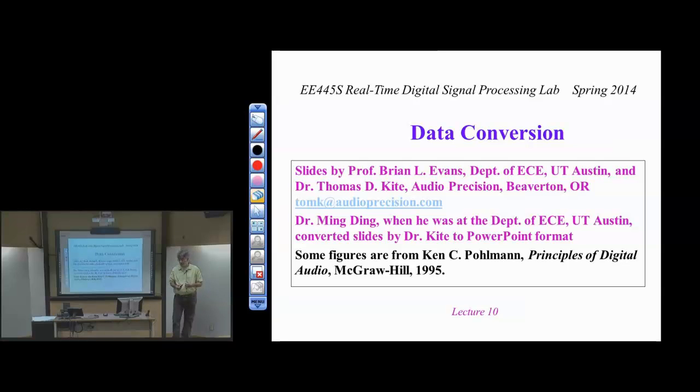The opposite would be, as you're listening to this, we now have a discrete time digital signal, and you'd like to play that back over headphones or possibly speakers. We want to convert that discrete time digital waveform for the audio back through a digital to analog converter, and then through a piezoelectric or some other device that will take the current and voltage from the digital to analog converter and get it back into pressure waves so that we can hear it. So again, either through speakers or through headphones.